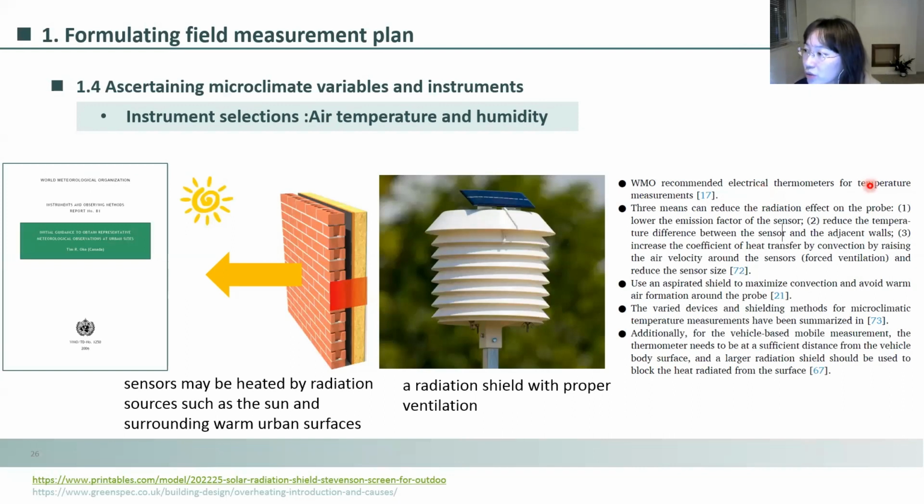Okay, after introducing field size, now let's talk about the microclimate variables and the instrument. If you want to select an instrument to measure the air temperature and the humidity, Oke mentioned in his guideline that the sensors in general meteorological stations are all appropriate in urban areas, including their accuracy and response characteristics. But when you put your thermometer in an outdoor environment, you will find that the temperature